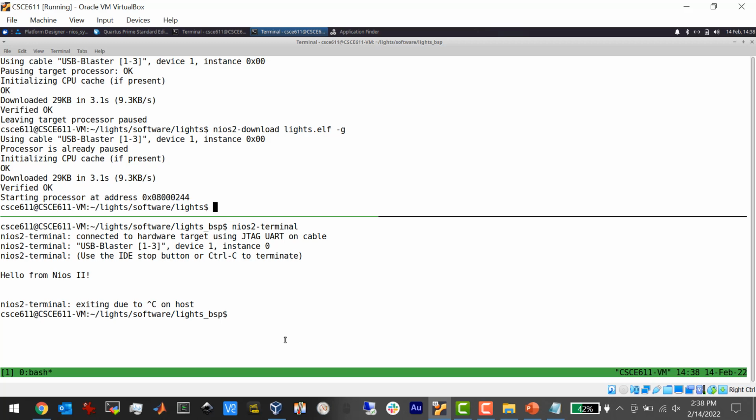So we can measure the passage of time, which is very important for doing control, because when you do control, there's this assumption that you have a control period, and every so often you execute: you read the sensors, you calculate the outputs, and then you actuate your system. Does that make sense? Now in this lab, you're going to use it for controlling the duty cycle and the period of the pulse width modulation. And so that's the whole reason we've got that in there.